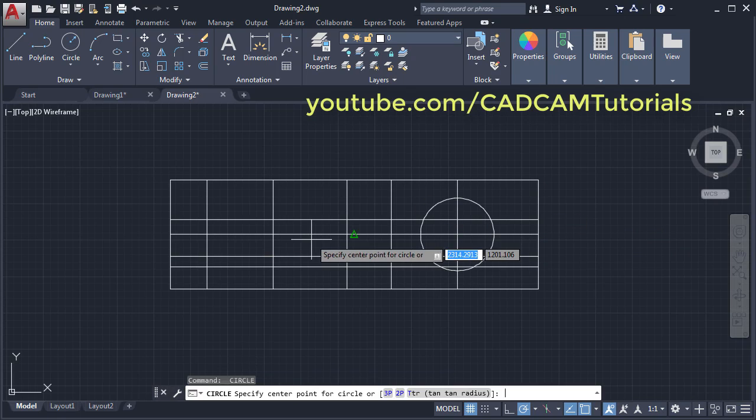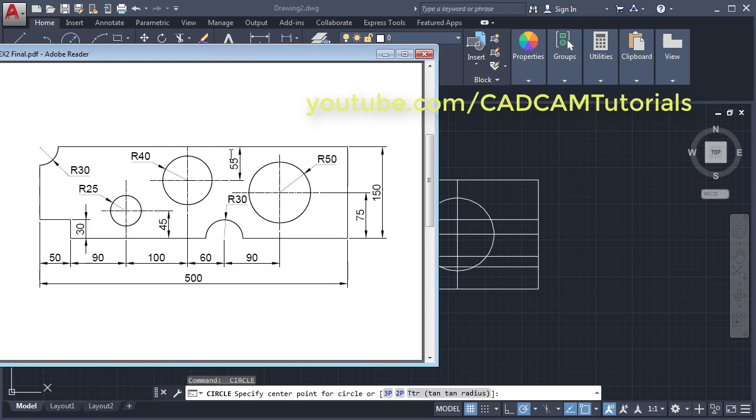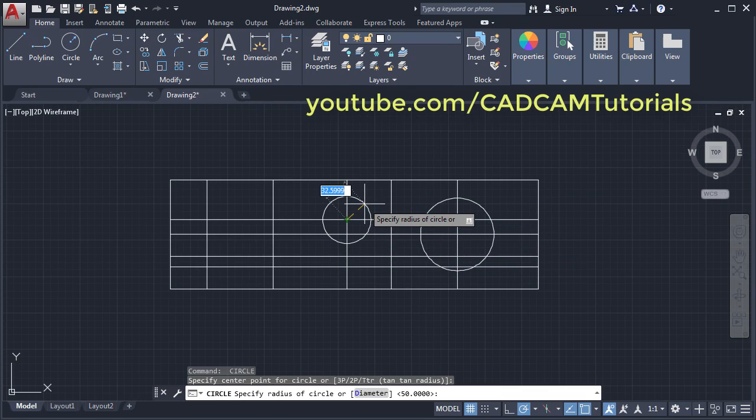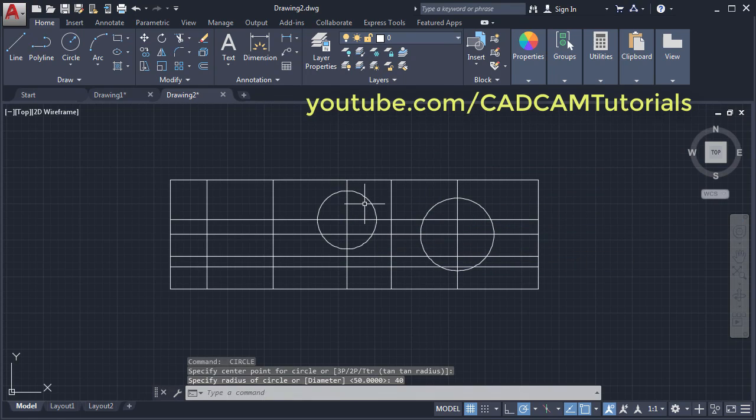Then again enter. Next circle is 40 and it is on the third line and first line from the top. So here is the third line and first line from the top and radius is 40, enter.